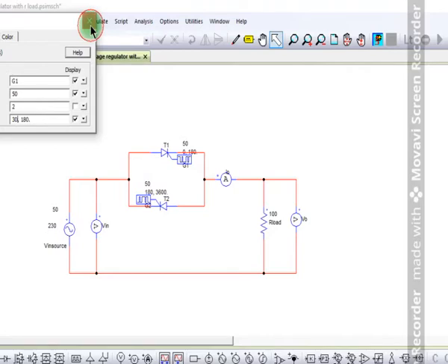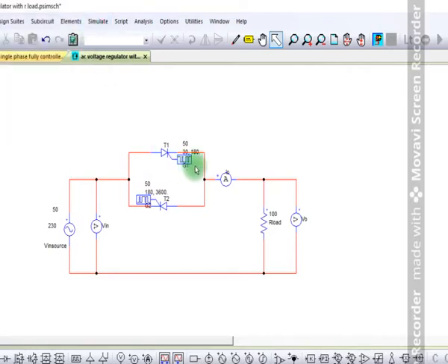We can observe here one thyristor, that is T1, we have given a gate signal, gate pulse, that is the firing angle which is given for T1, that is 0 to 30 degree. From 30 degree to 180 degree it will conduct. From 0 to 30 degree it will not conduct. And then we come to this T2, that is thyristor 2.